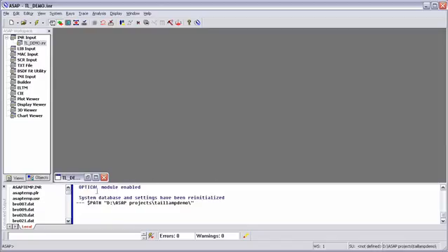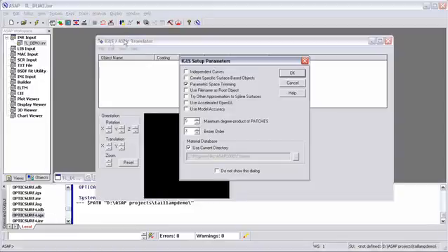Now that we've got an optical surface, we can go into ASAP and convert those into geometry that can be used to simulate the part. If you recall, we saved our file out of Rhino and we call it OpticSurf4. I'm going to double click this, and this is going to bring up the IGES translator.